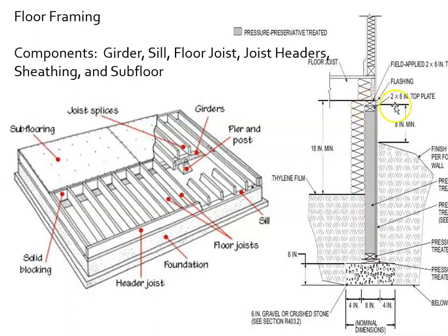And then right up here, they're calling them top plates, but actually if this were a concrete wall, that would be a single sill right there rather than a double top plate. But building pressure-treated walls under the earth is really uncommon. But same difference, really. If this were concrete, there'd just be a single plate there, and then the joists come, and that's what we have right here. So sill being wrapped, joists extending from the load-bearing. This is a load-bearing foundation wall. Same on the back, load-bearing.